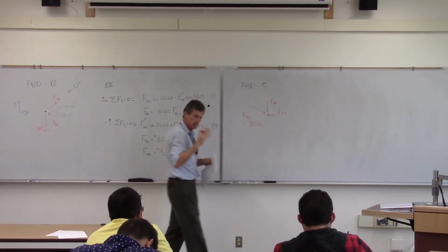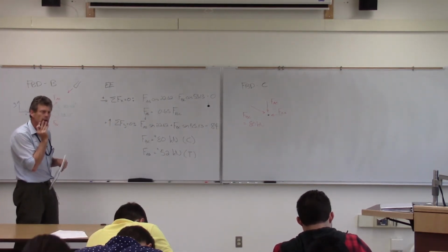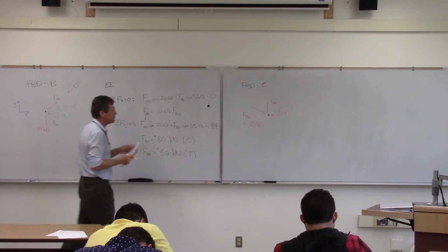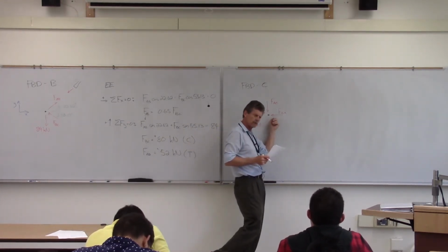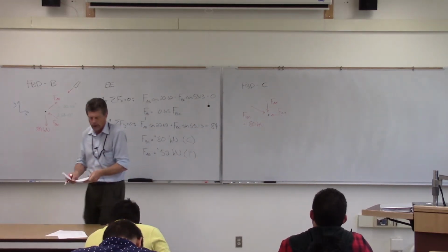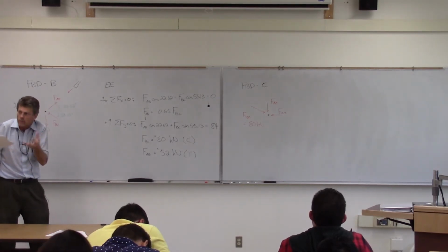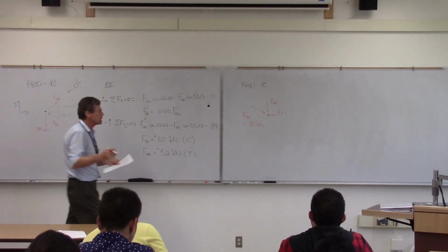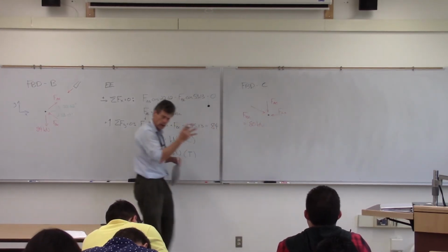And then the other 2 forces there are going to be the AC component. And the one thing that a lot of people tend to forget, and I'll see this a lot in joint analysis, is they'll forget about the support. When we look at that, the support there at C is going to be providing a horizontal component. It's providing force at that joint. A lot of people tend to forget this piece. So you're not going to forget it. We're going to hit it into you.